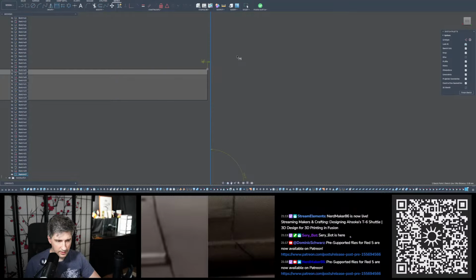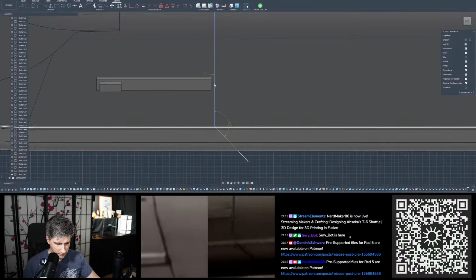There should be just a little bit of space. So let's make this 0.5. Pen line will be 0.5. 0.25 on the left side, so we have 0.25 space to this thing. I think that should do.